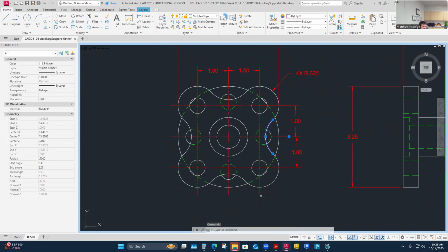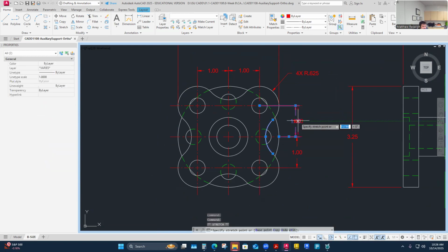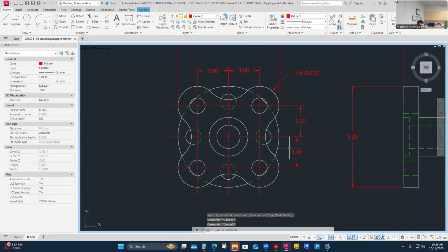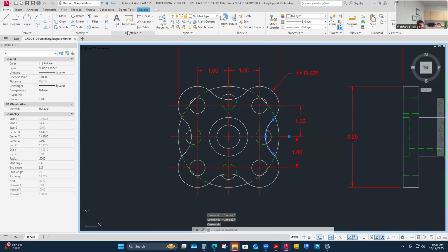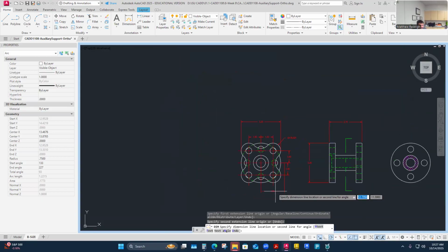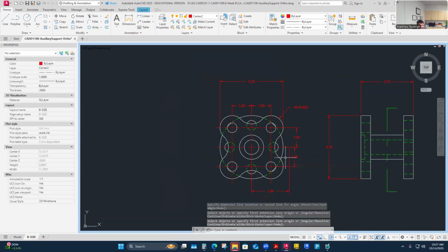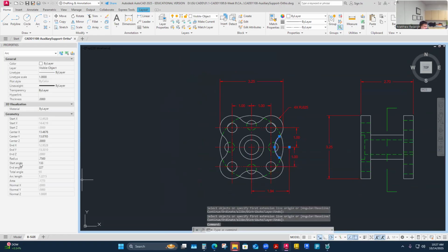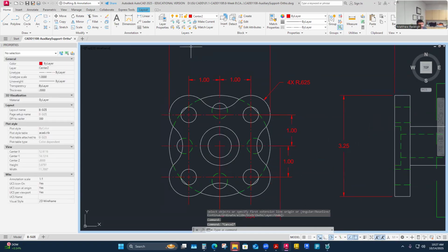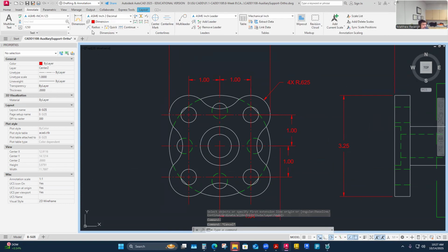I argue that this one, to continue to do rectangular, I think this one's going to be better as a polar. Otherwise, what we need is where the center of this is, right? And to locate it in a rectangular fashion would be from here to wherever this center mark is there. You know, it's 0.194, and that would be fine. Like this is locating this center mark here, which I can probably put. I may have to put a center mark there. Let me see what that would look like just real quick. Center mark.